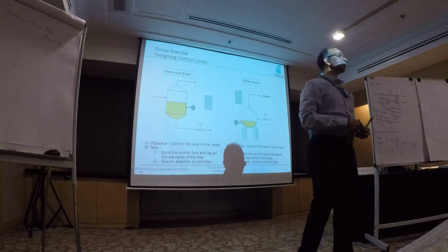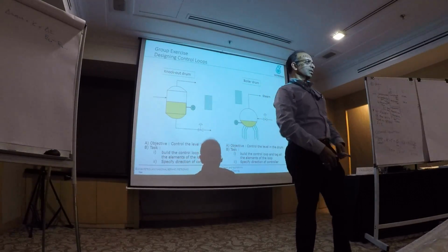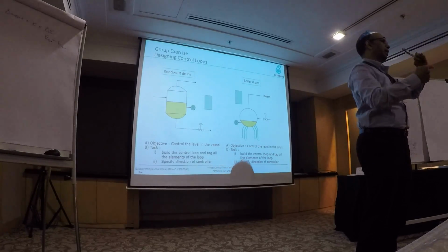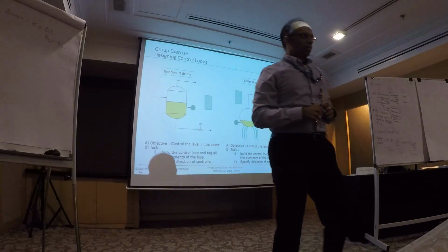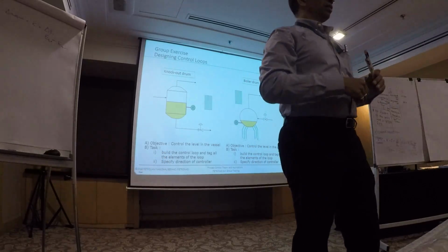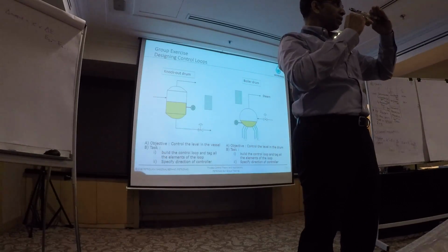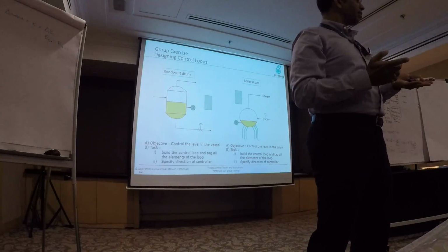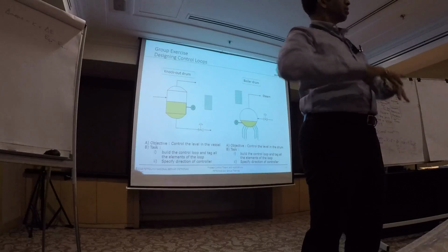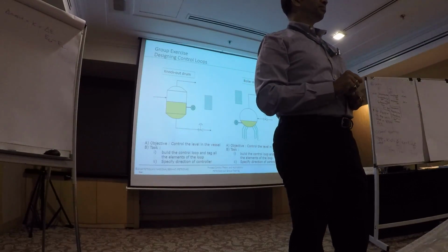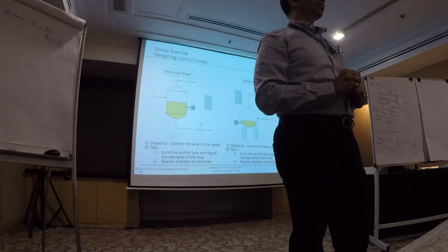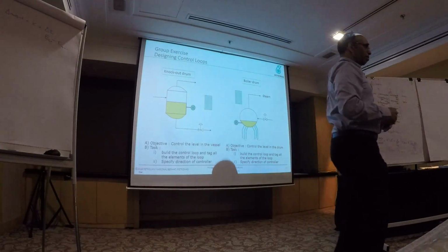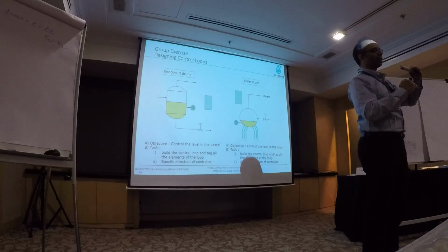So let's go through that same scenario one more time. Suddenly level drops. I get 50, 40, I calculate error 10%. Second time I process, I calculate error 10%, but the last error was 10%. So the delta error is 0. No change in output. Okay? Now, to answer your question, strictly speaking, the first time I run it, I get 10%.